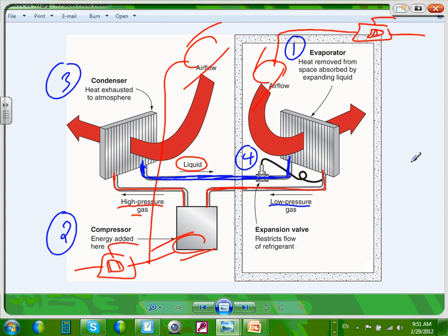Or it could be a rooftop unit. Rooftop units are very similar, guys. A rooftop unit could be one package right on the top that throws air, hot or cold air. They add the heat to it too. Or it could be a split rooftop unit where you have these 2 pieces, condenser and compressor, in one location, and the evaporator inside the building. So you can have a lot of packages for them. Okay, when you go to a bigger system, and I'm going to stop right here because it will come into it. Now this is a smaller system. You go to a bigger system.